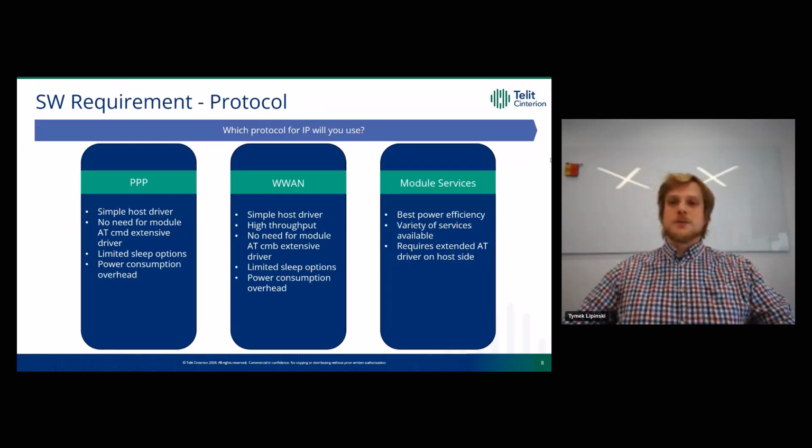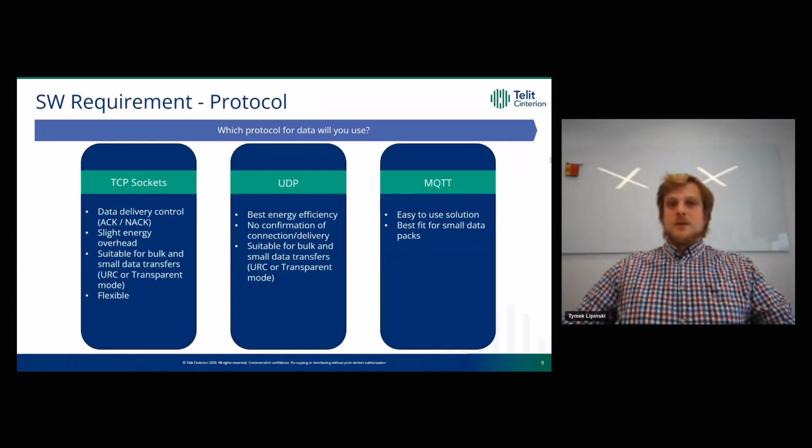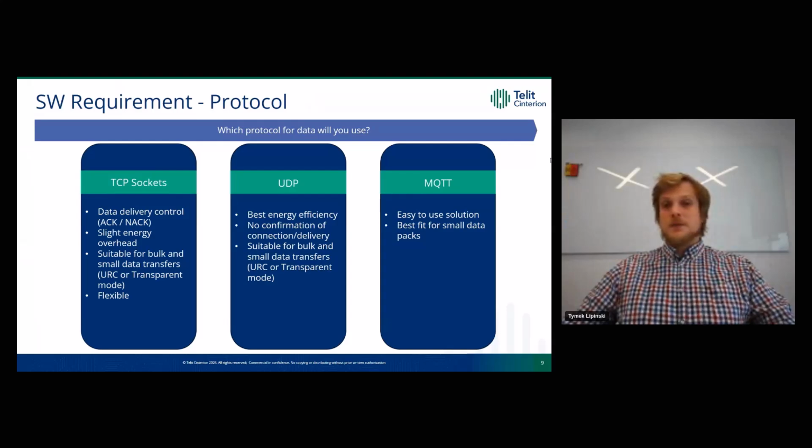On the other hand, module services, which are integrated into the module AT interface, provide the best power efficiency. They have a variety of services available. Unfortunately, they require an extended AT driver on the host side. Which protocol will we use for the data itself? Will it be TCP sockets, UDP, MQTT, any other? Well, it depends on what we are trying to achieve with our application.